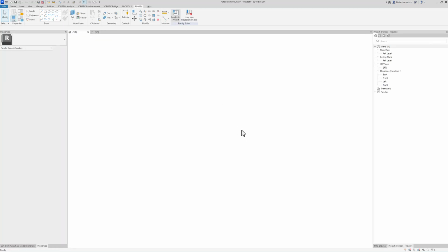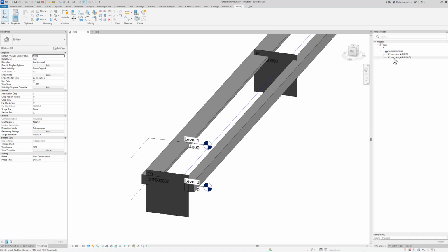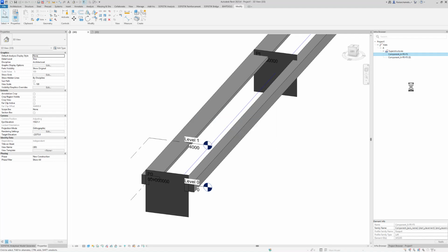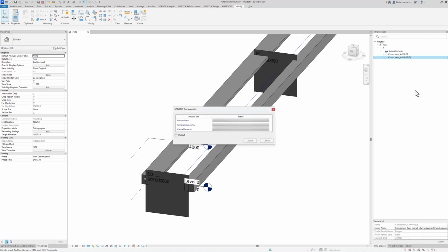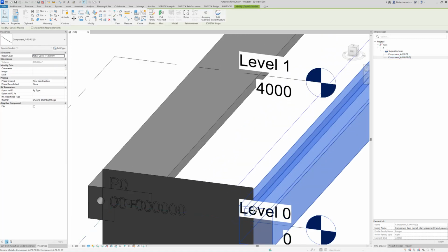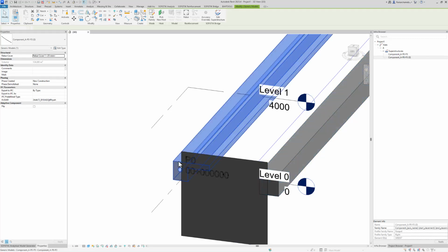Simply by loading into the project once more, you can now go to the already existing components and tell the program to refresh them. So I select the first boundary and click on refresh. The program does not require you to access the superstructure command once more, but it will create the volume accordingly. Click on refresh for the second one. And we can take a look at our openings in the geometry.